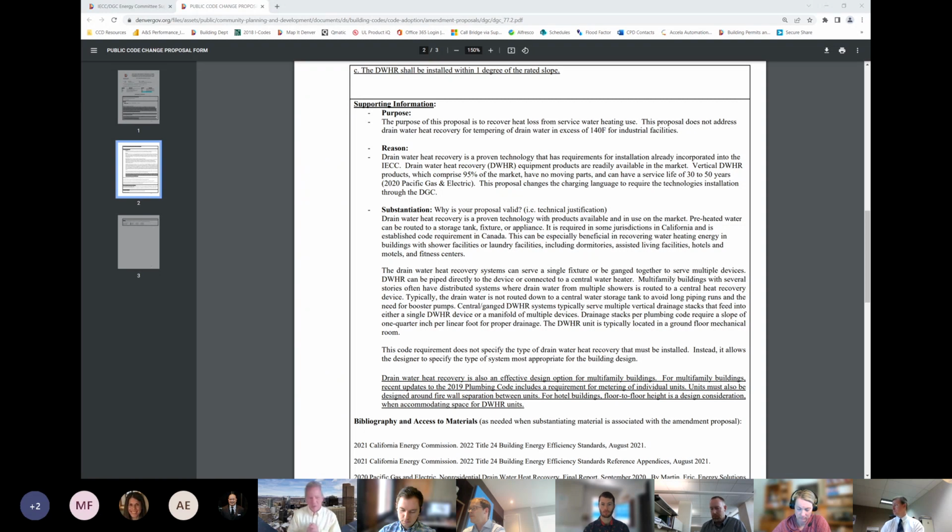Now, that also requires a thermostatic shower valve, because otherwise the temperatures get all out of whack when sometimes the water is cold and sometimes the water is hot. This is why it does belong in the green code, because it gets interesting to actually apply it. It works well on gang showers because you get a whole lot of bang for the buck, a lot of drains, and one master valve that you have to take it back to.